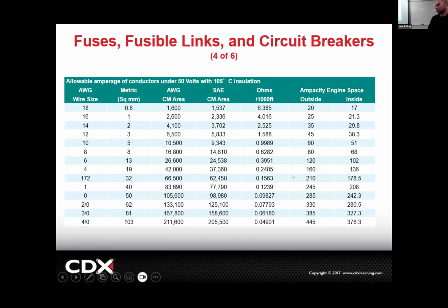Okay, make sense? So if you've got a 10 amp fuse that's blowing, you can't put a 15 in there. I guarantee you from the factory, that wire harness is not made for 15 amps. If it is, why would they waste the money? They make hundreds of thousands of that vehicle. They wouldn't put too big of a wire times hundreds of thousands. That's hundreds of thousands of dollars. Make sense?